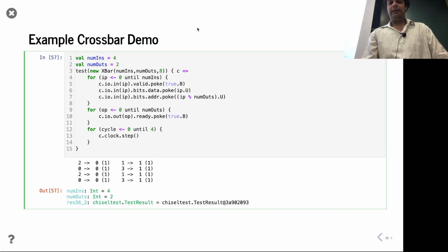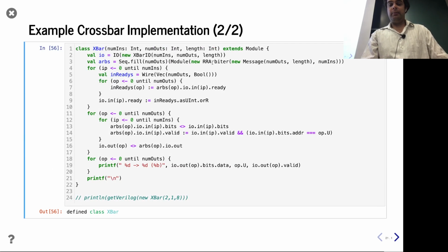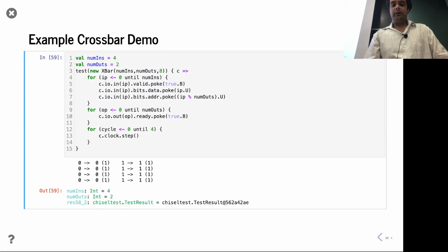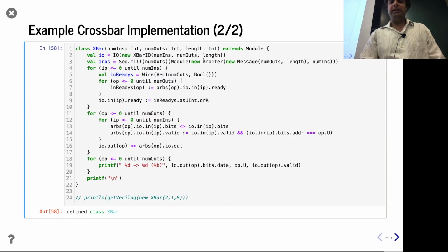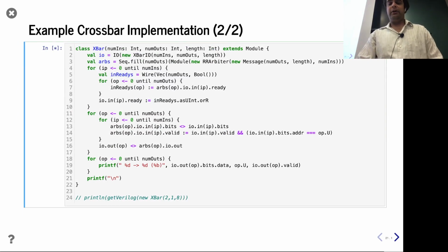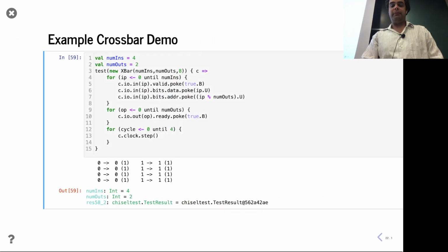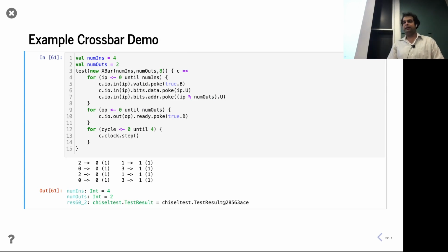So if I go back and say, hey, let's maybe not be round robin, we're going to have a constant winner. It's always 0 and always 1. But yeah, that round robin arbiter is a 2-character change, right? And in this case, they really are equal. So having that round robin behavior is perhaps nice. Might complicate testing later on, depending how you have your testing bed set up. But hey, that's kind of cool.